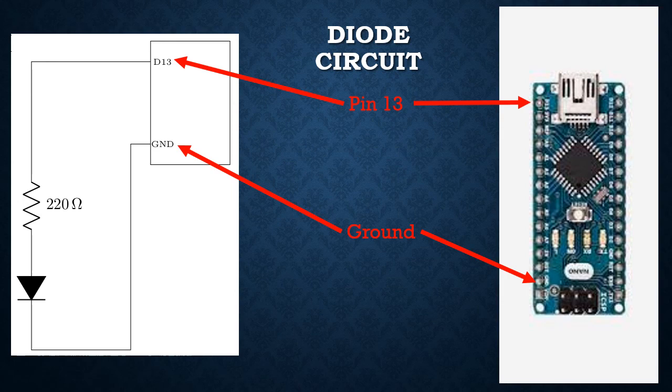And then once you've selected a row, you want to find a 220 ohm resistor. It's one of the fixed resistors, one of the striped cylindrical resistors that you have in your kit. We will talk about how to identify the resistors with the striping at a later session. But for now, what you want to do is look in your kit, and you'll see that the resistors are bundled together with brown tape at the top, and you want to find the set of resistors that has the marking 220R. And all of those resistors are 220 ohm resistors.